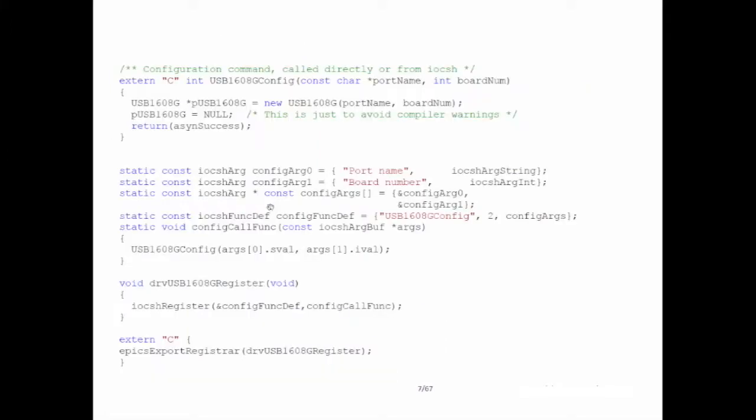Now, one thing that I didn't mention, but it's worth mentioning, is that we've got a parameter list in the asyn port driver for each address. So in this case, there's going to be 2 parameter lists, one for the first analog out and one for the second one. It's somewhat inefficient because often there's a whole bunch of parameters that really belong to the box, and then there are parameters that belong to each subaddress. And what we're doing is not distinguishing that.